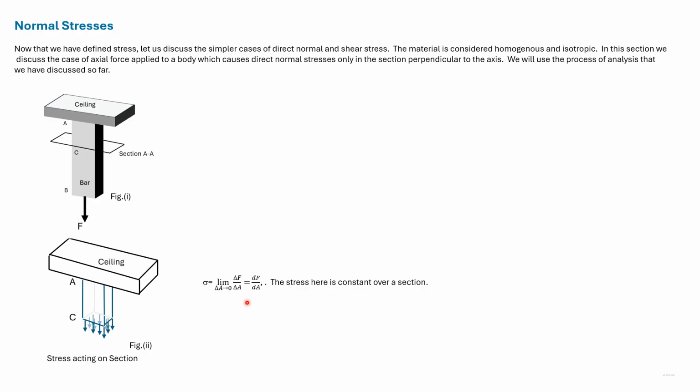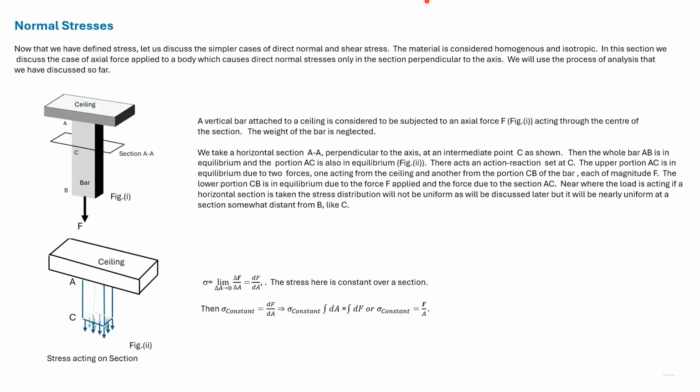Now consider a small area within the section, del A, and let the force acting on that area be del F. Then the stress acting on the area is equal to the limit as del A tends to 0 of del F divided by del A, which is equal to dF divided by dA. Now the stress in this perpendicular cross section is constant.